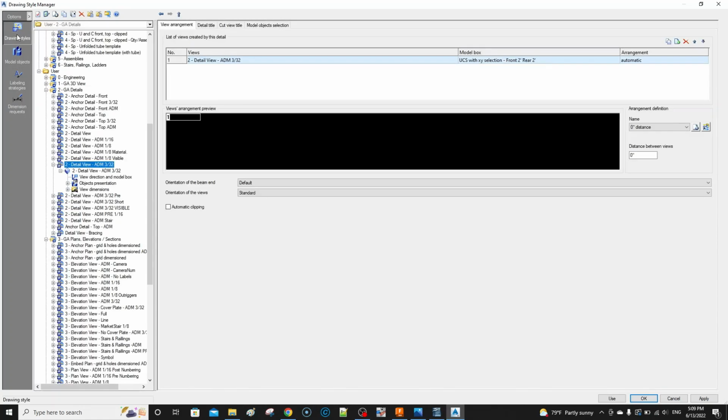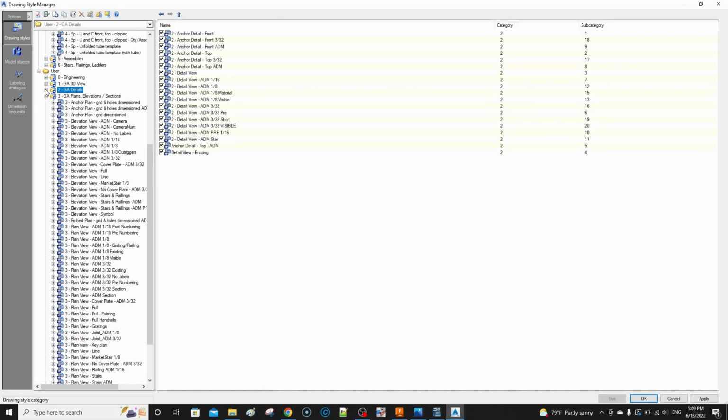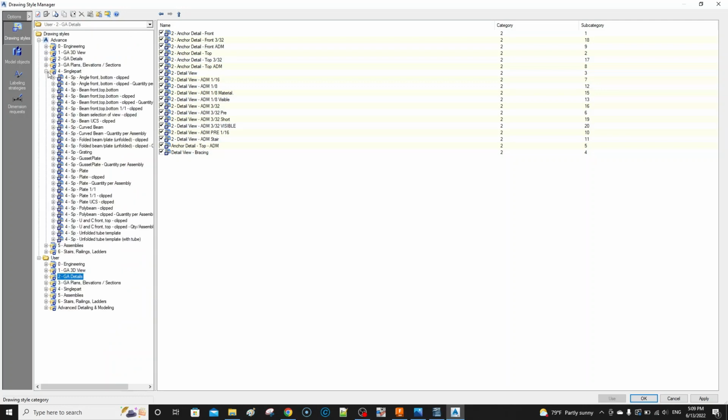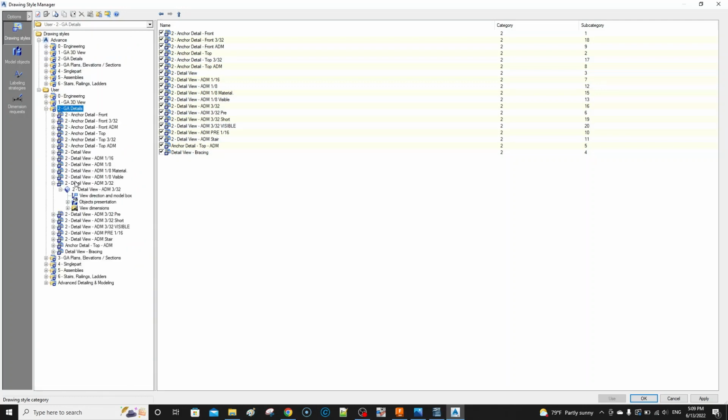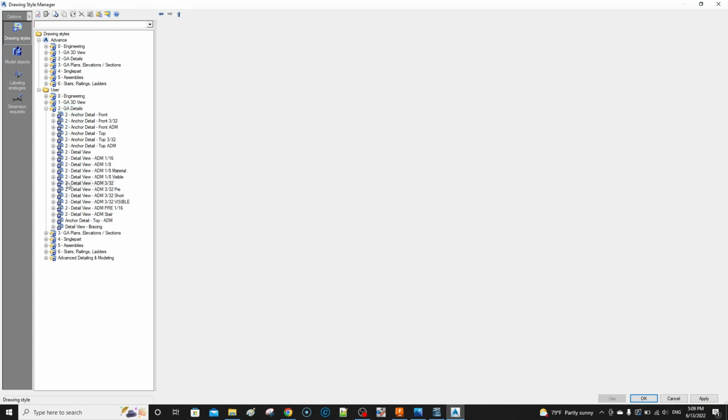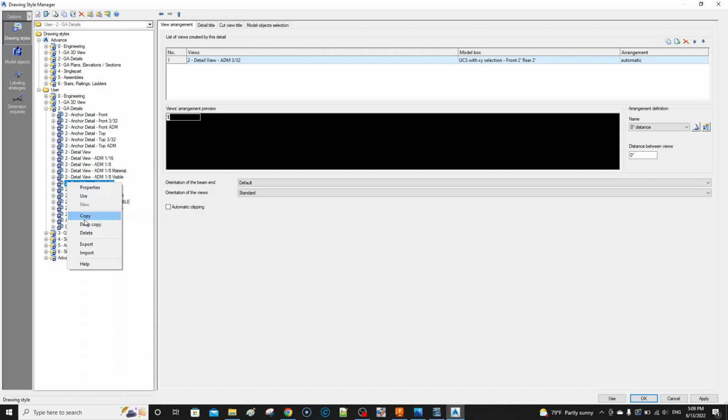The most important thing for you is to be able to create new drawing styles. I have other videos on that. Basically, come into your drawing style, right click and copy, not deep copy, just copy. Rename it, then you're going to go to the next level.